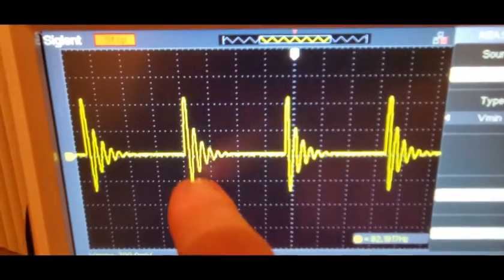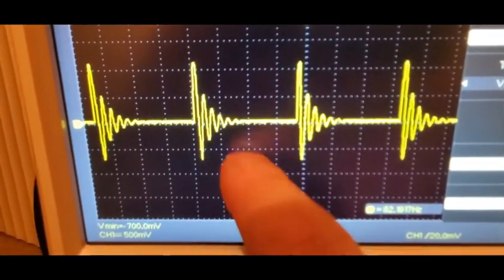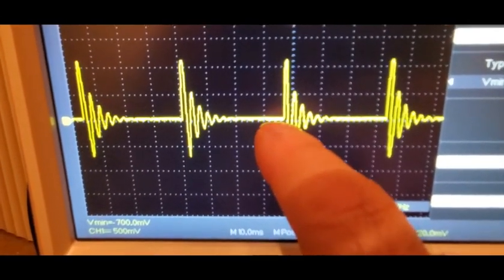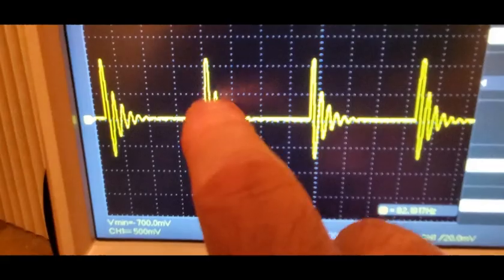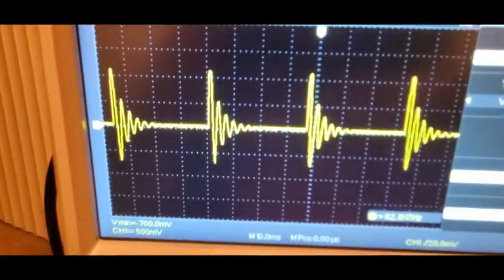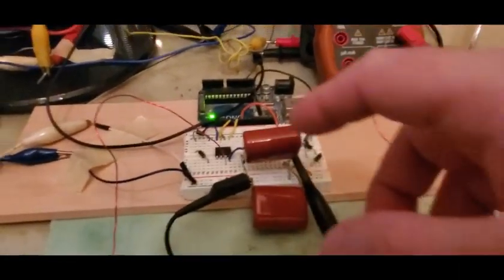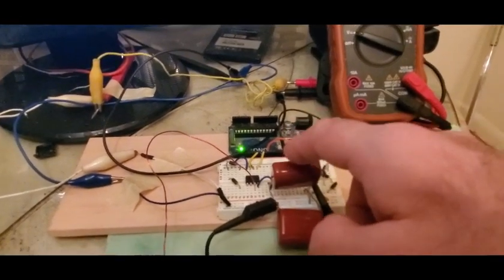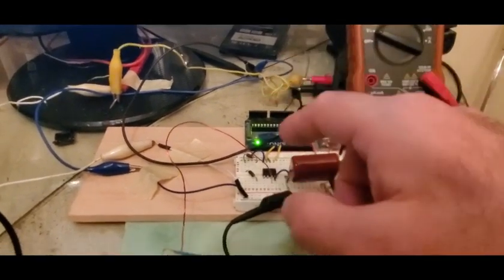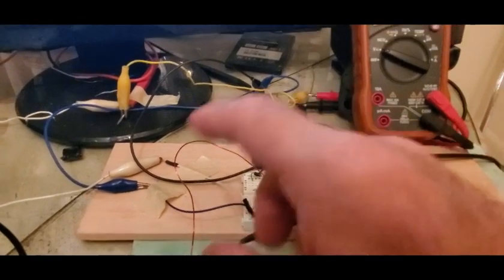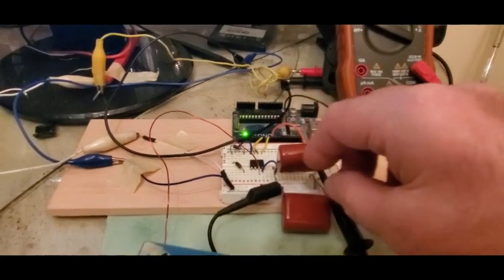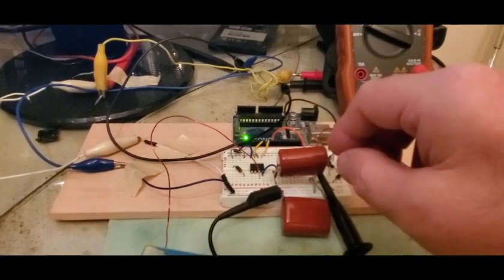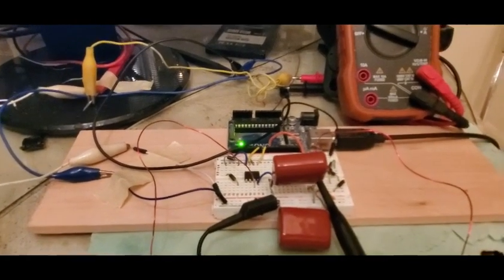So that's what this LC tank circuit looks like after 12 oscillations. It's pretty much gone. It's just damped out entirely. 1, 2, then nothing. Okay, so when I was doing this, for some of them, I was going like 20, 10, 4.7, 2.2, 1, 0.47, 0.22. Let's just jump from 20 to 4.7 and see if we get an improvement in the Q factor, all right?